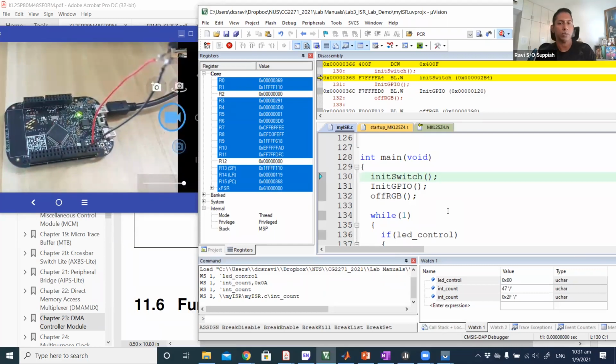I think everybody knows the reason, correct? What is the reason? Why the first few times it didn't stop, and then now it suddenly stopped? Yeah, correct. It is debouncing. We have seen this before as well. A mechanical switch is going to generate a lot of pulses, so that is definitely an issue. We can deal with it with whatever technique you want.